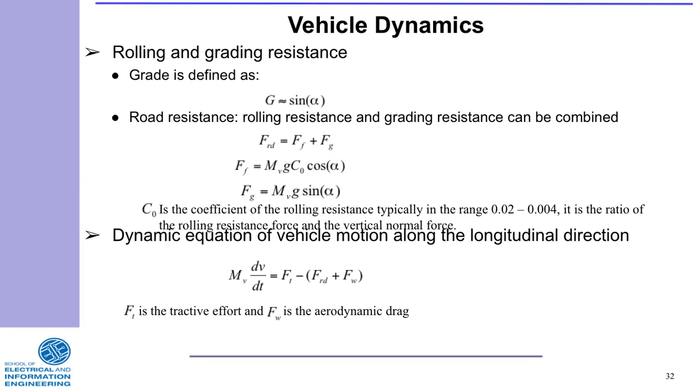Now, going back to the vehicle dynamics, these are just the equations that describe the rolling resistance, for example, and the gradient resistance, and as you can see, it's a function of the mass, the weight, and these two factors there that are probably functions of the characteristics of the tire and so on. And then back to that normal equation where you are saying the tractive force, the difference between the tractive force and the forces opposing motion on the vehicle, the loading, the weight, and so on.